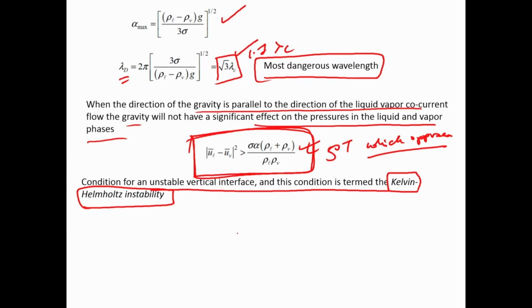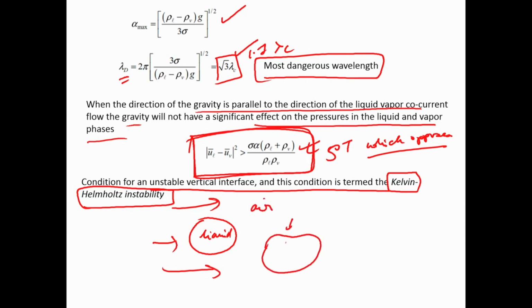it is also the dynamic behavior of the interface that is very important, because when you do heat and mass transfer analysis, especially say you take the configuration when a liquid droplet is put into a flow of air, what happens? The droplet actually should get perturbed. This is an interface between the droplet liquid and the air, and there is a flow, there is a recirculation inside the droplet, there is a flow outside, and there is a huge difference in density, this delta rho is large.